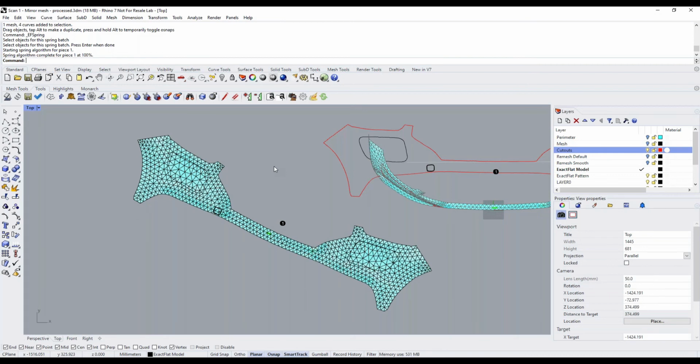My understanding of the VX Elements flatteners is that it's brand new, and it's primarily for more developable surfaces. These are surfaces that only have a curvature in one direction. So that is a point to take into consideration here. You'll need to make the right assessment for yourself. If you're doing cylindrical or non-developable surfaces, you'll have to test it and make sure.